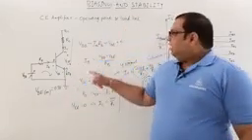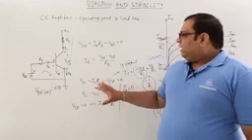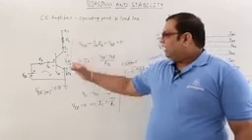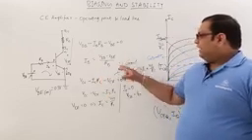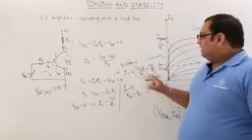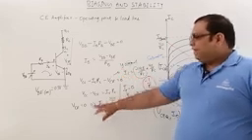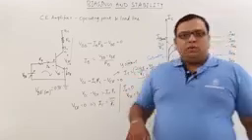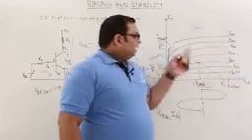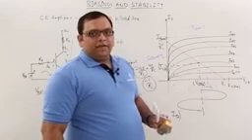So this is about finding the operating point and the importance of load line. We can get the load line from the output characteristics. Just take the output equation and write it in terms of y is equal to mx plus c. This equation gives the equation for the load line. By taking IC is equal to 0 and VCE is 0, we will get 2 points. By connecting these 2 points, we will get the load line, and the middle of the load line we will always take as the operating point.